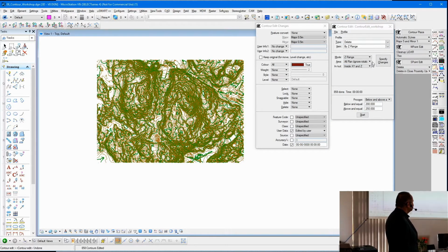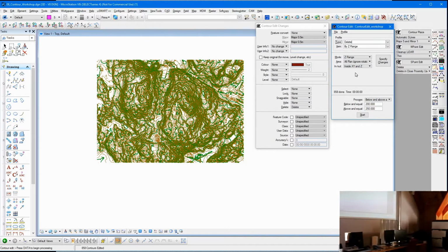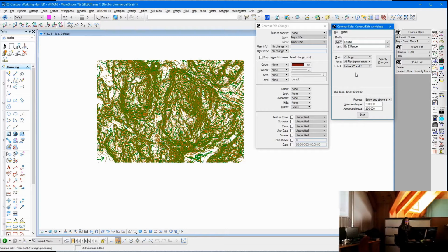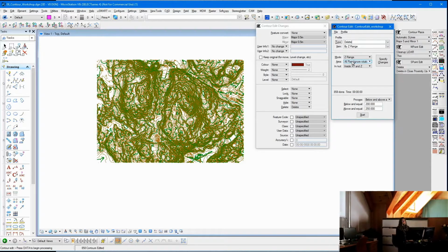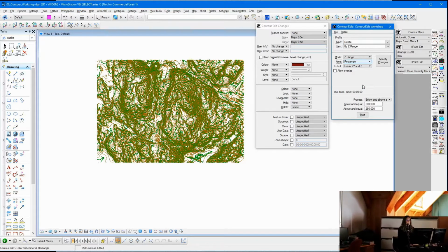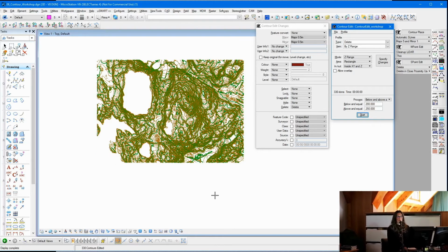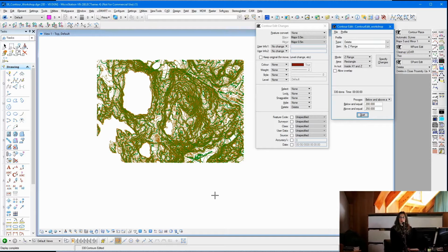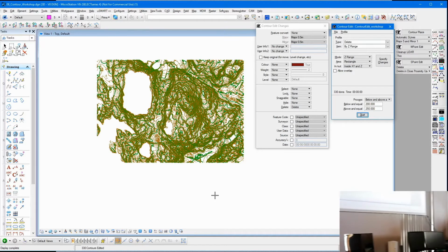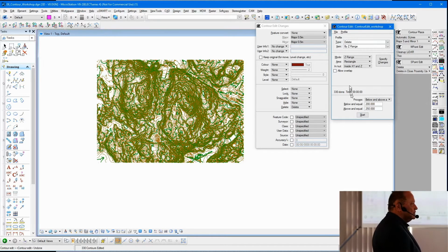Okay, so we also just want to make you aware, if I just do a reload here quickly, so if I do make a mess of it, the reload will just take it back to where it was. Then the area option. So you might say, okay, I don't want to do the whole area, just want to go inside my rectangle, and I'm not going to switch on the overlap, and we're going to delete inside there. Okay. So now we've still got the height. We're still working within that height range, but we've added a further constraint. And we said, no, only within that area, and remove the height.